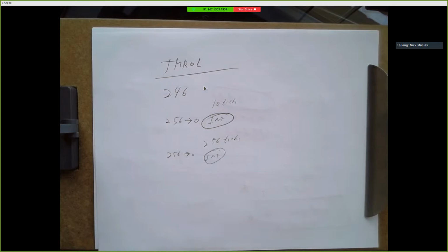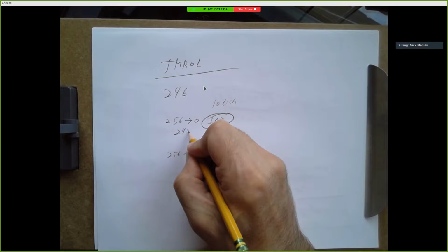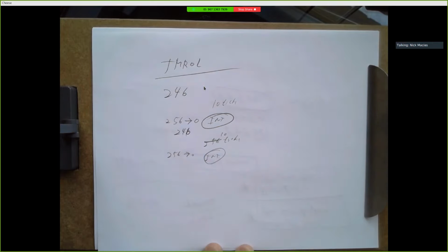If I want it to interrupt repeatedly after 10 ticks, what I need to do in this interrupt code is reset this to 246. And then after 10 more ticks, it overflows. Right? But you have to write software that says when you get an interrupt, let's reload this magic value into the timer register. You don't have to do that with timer 2.